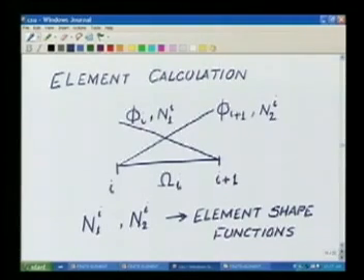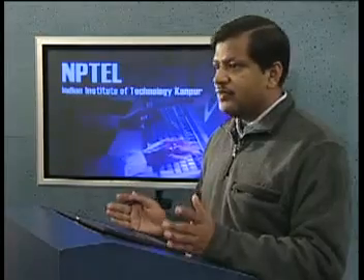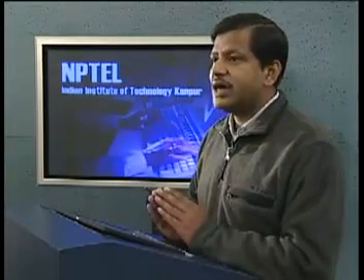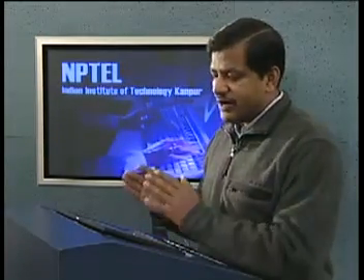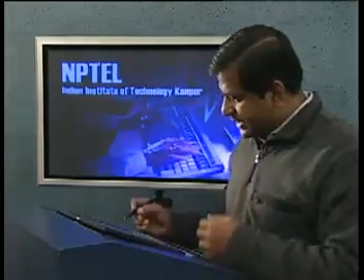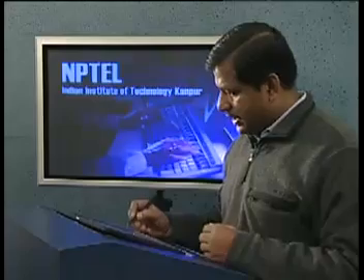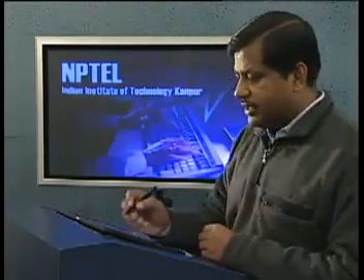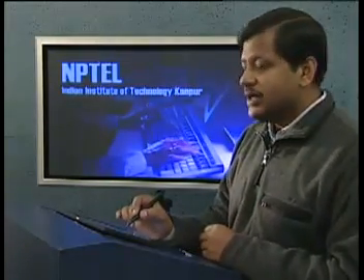So you have to understand that the element shape functions are nothing but the part of the global basis functions phi i's which are non-zero in the element I. This way we will have the shape functions for each of the elements. So what we are going to do next is, if I look at the finite element solution in this element